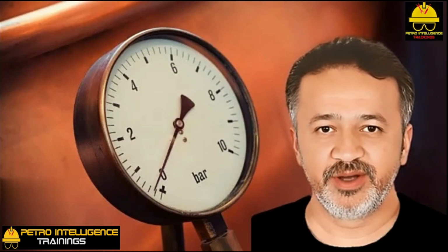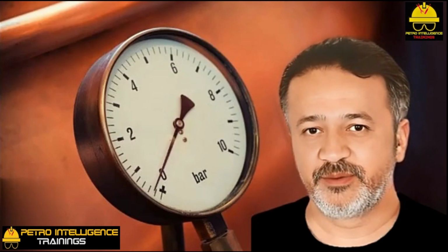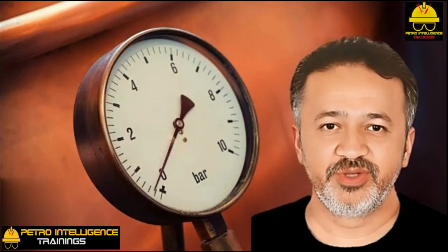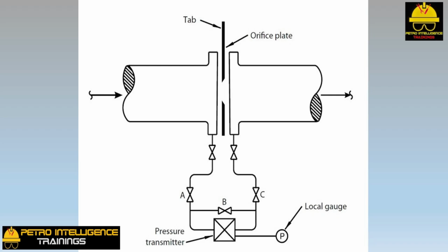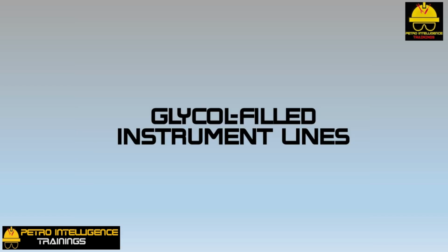More commonly, we have rotameters, which measure how far a ball or float is lifted in a vertical tube by the velocity of the liquid. But regardless of their relative merits, perhaps simply for historical reasons, the vast majority of flows in most process plants are measured with the orifice plate flow meter, as shown in this picture.